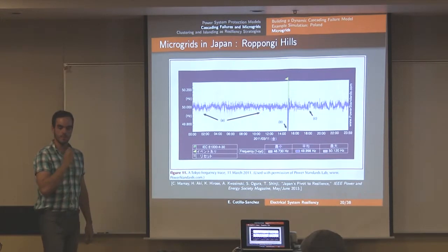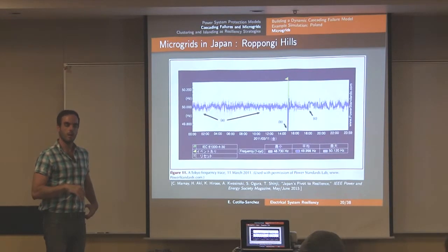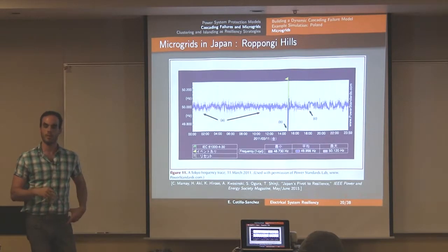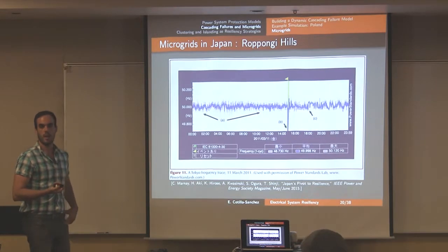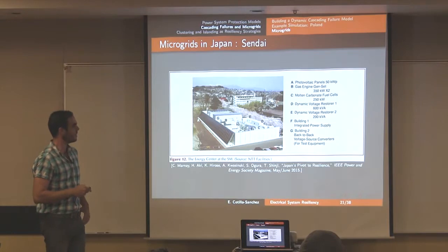So the type of simulation that we had before could look at things like low voltage ride-through, what the frequency excursions are, how the controllers and your relays are behaving, and then whether you really have a lifeline supply for your local sources. That's one of the things that they learned.